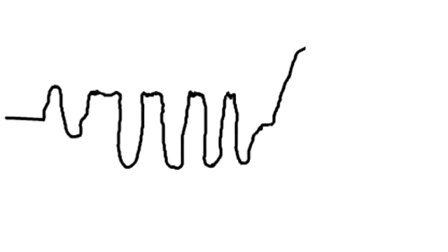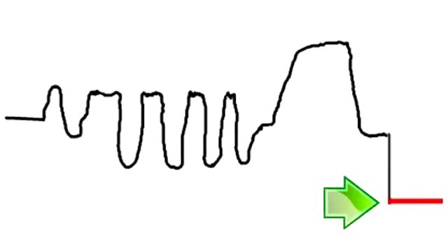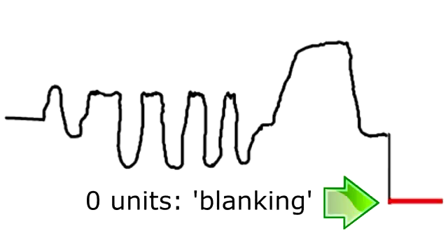Once a line of picture information has been sent by the camera, the video falls below 7.5 units to 0 units, well below the level of the darkest portion of the picture content. This tells the monitor to stop displaying video information to the viewer, and is called the blanking signal. It blanks out the picture content. To ensure that our picture monitor scanning doesn't drift off frequency over a long time, which would skew our picture in unpredictable ways, we send, in the middle of the horizontal blanking period, a horizontal sync pulse. This gives the monitor a reminder to resynchronize with the camera scanning at the end of every line.